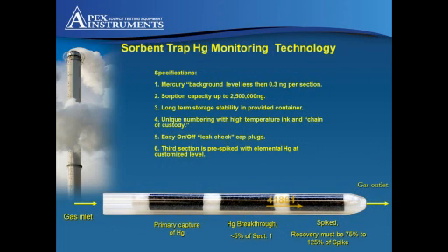That's typically what a 3-bed sorbent trap looks like. The test is always carried out by paired sample trap collection. The sorbent traps conform to the PS12B standard sampling analysis specifications. High concentration of iodine deposited on acid wash activated carbon ensures extreme mercury capture capacities without breakthrough for extended test periods in wet or dry stack emissions from coal-fired power plants.